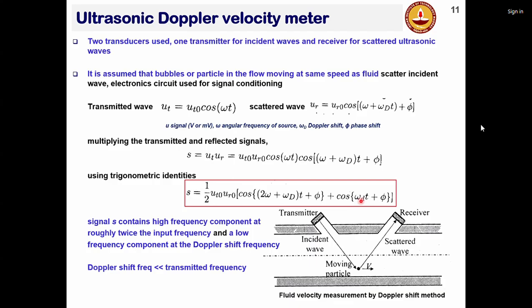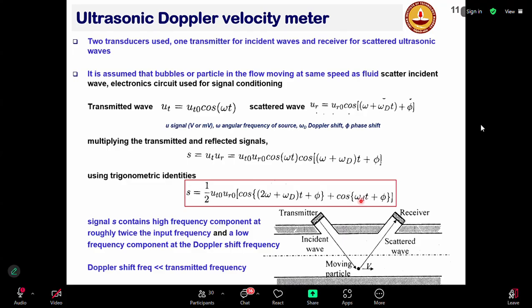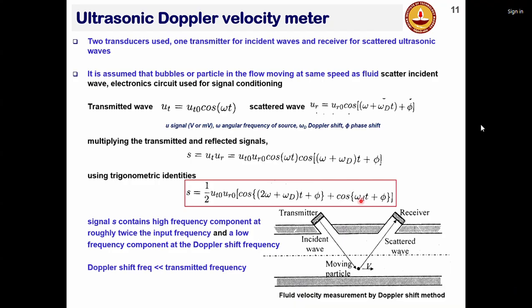From fluid dynamics theory, if the particles are very small, they flow almost at the same velocity as the fluid, whereas bigger particles would have a very different velocity compared to the fluid. That's why people use very small particles. They are easily dragged along with the fluid element and have almost the same velocity as the fluid.